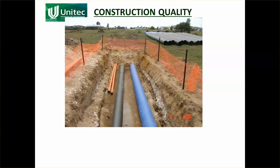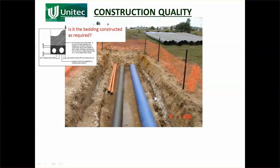So, construction quality. Here is a couple of pipelines. The blue one's a water pipeline, the black one's a wastewater pipeline. I was actually the designer for this, and I'd put a whole lot of drawings and specifications there. Those pipes are sitting on bedding, and I had specified what the bedding is. I'd drawn a picture showing where the pipes are, what the distance is between the pipes, how much bedding is underneath the pipes, and how much bedding is going to be on top. You can see that they haven't put the bedding in yet. By the way, that orange there is ducting.